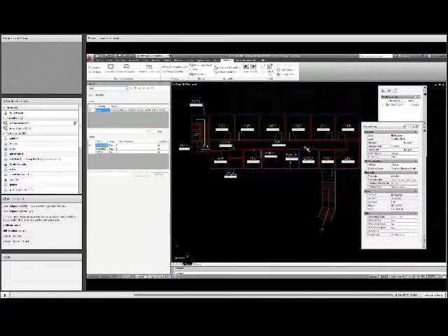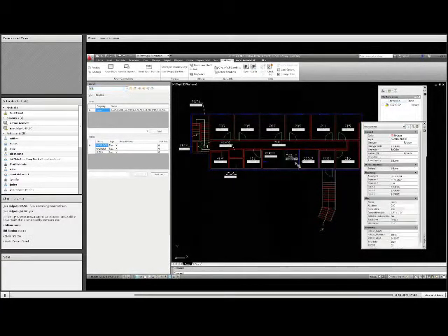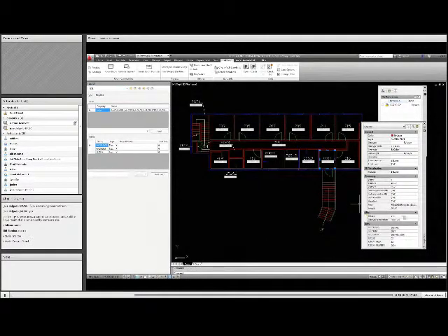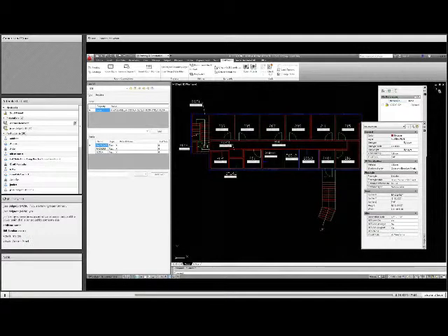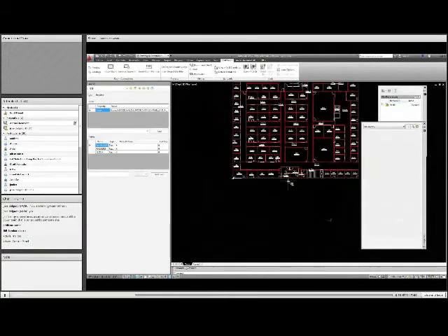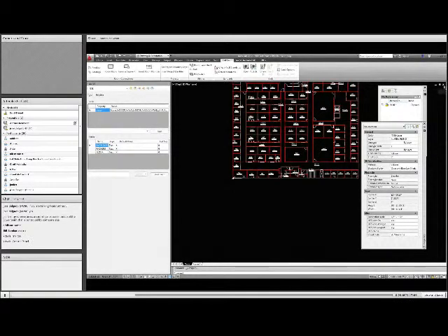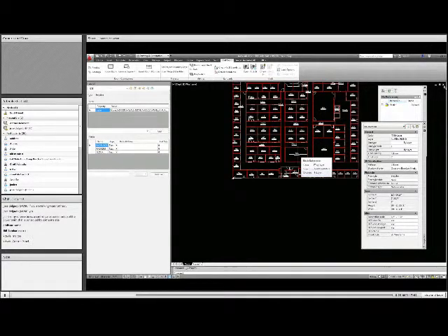I have another specialized floor plan called an outline, which is really just, ideally I would use the actual building outline itself, or ideally a structural roof plan that I can very easily reference the structure. So I have a complete tie between the floor plan and the roof plan and the building outline, and then use that same building outline in the site plan, and everything works out really well. But you can see here, if I xref in my floor plan, it's really perfectly aligned. In fact, I think this is actually the GSF boundary that was created for that. So the building outline really represents the coordinate system of the building.